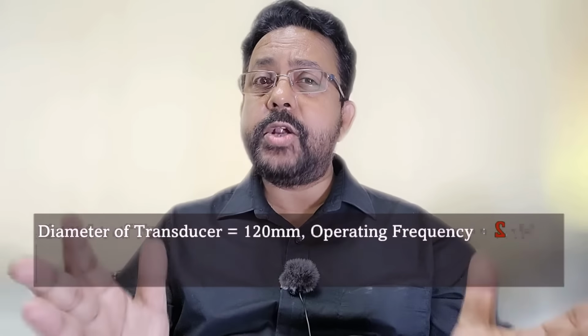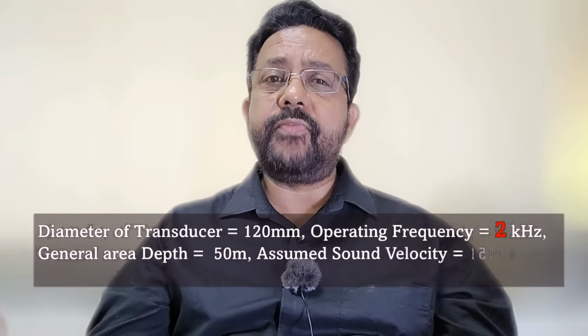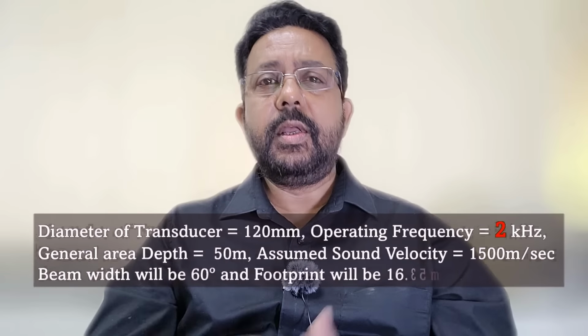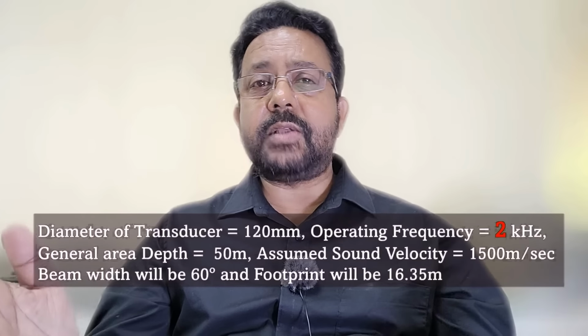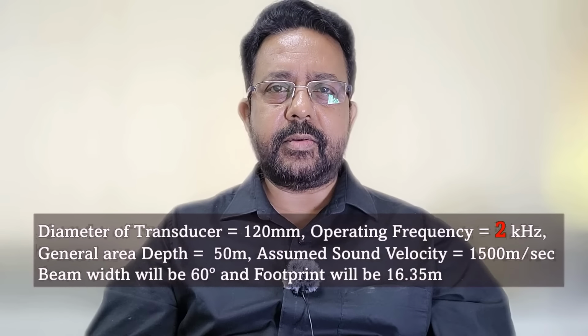Now if you want to study how big your beam width will be and how much footprint it will have on a seabed, you can use some formula and take a wise decision before you go for survey. Suppose the dia of a sub-bottom transducer is 120 mm and the operating frequency is 2 kHz. Suppose the general area depth is 50 meter and we take the sound velocity as 1500 meter.